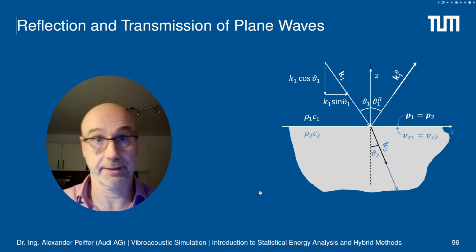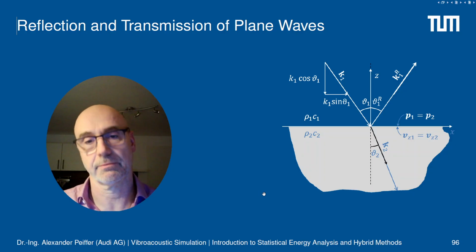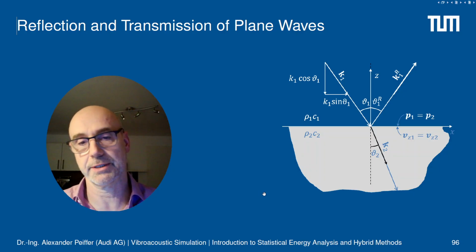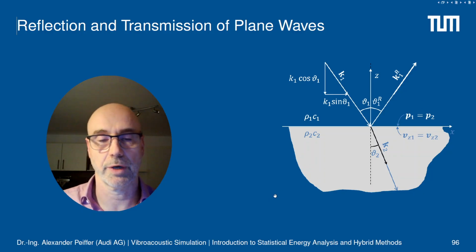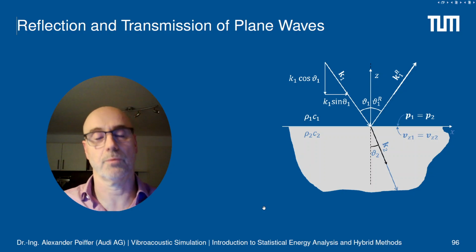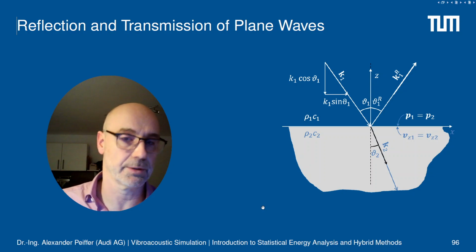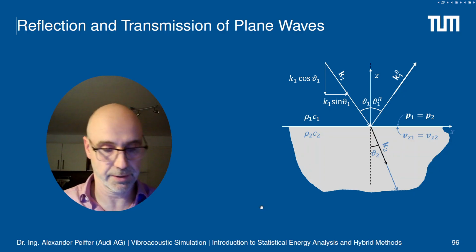That is quite an academic problem, but anyhow it's a first hint on how acoustic wave fields are coupled between neighbored systems, in this case two areas of fluids. And you will learn what is the determining property, so which property defines the coupling of those different wave fields, and this is an important first step in SEA towards the coupling loss factor.